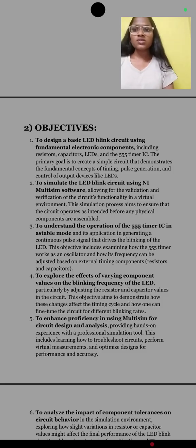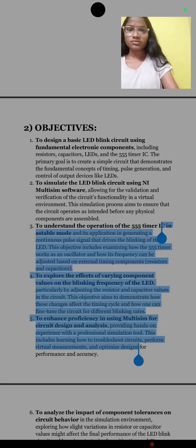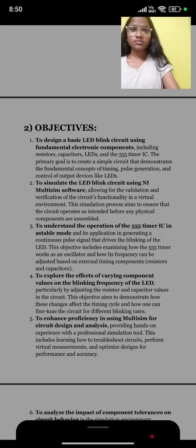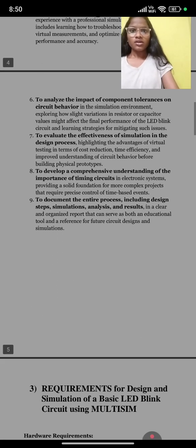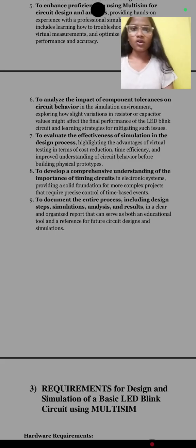simulation tool. This includes learning how to troubleshoot circuits, perform virtual measurements, and optimize design for performance and accuracy. To analyze the impact of component tolerance on circuit behavior in the simulation environment, exploring how slight variations in resistors or capacitor values might affect the final performance of the LED blink circuit, and learning strategies of mitigating such issues.